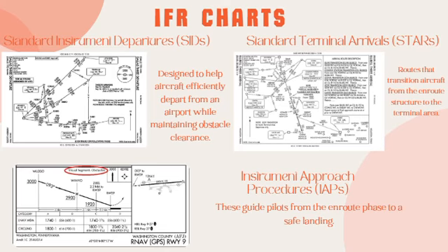For pilots, STARs help by providing a predictable descent path that minimizes ATC instructions and prepares them for the approach phase by aligning the aircraft with the selected runway. STARs ensure smooth and controlled arrivals, reducing the risk of delays or confusion.